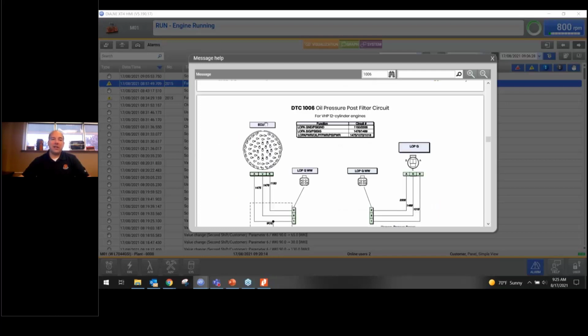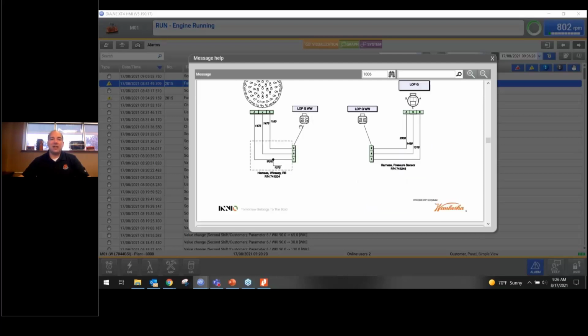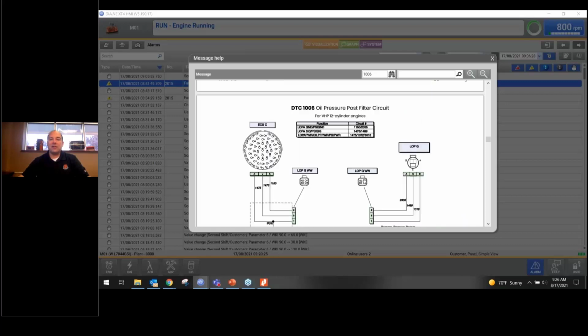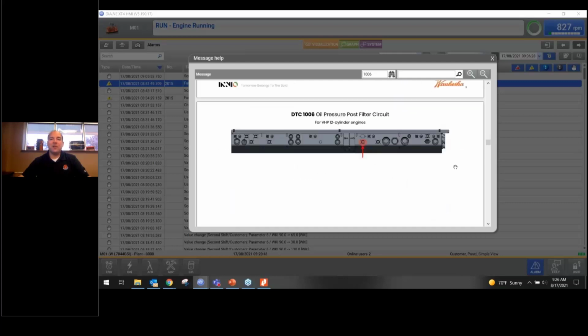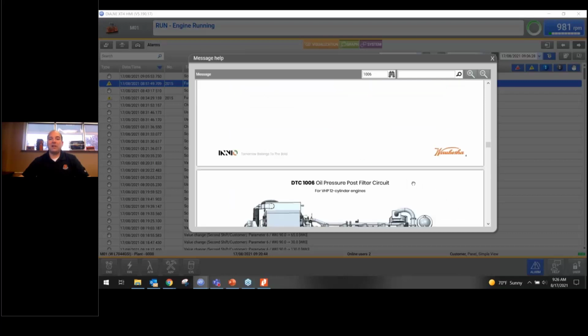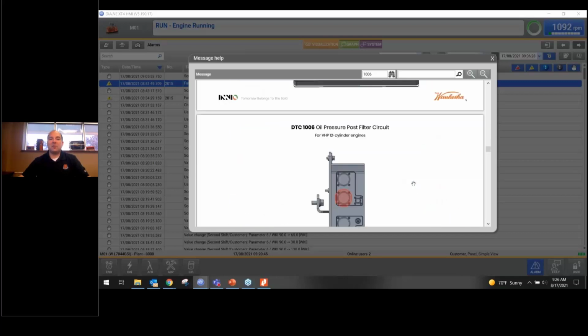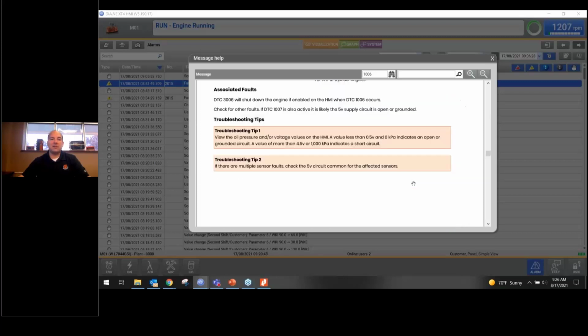It then goes in and it says, okay, here are my harnesses, and it's going to show each connector if we were going from the right bank and then coming over. And we see how this comes, and we've got our 1, 2, and 3 connections, and then we see where A, B, and C are located. And it describes what the wire numbers are and what their function is. So you've got the on-the-wire identifier, as well as the number identifier, and then the pin connection there. Again, we go back to where our connection would be on the rail, as well as then where it connects up to our ECU.